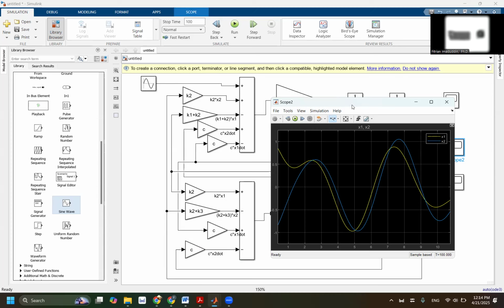But you understand that you still have all of this that's connected to this, connected to some other variable at the beginning. Minus C suspension x car dot, minus C suspension x wheel dot, minus K suspension x car, minus K suspension x wheel. This is the K suspension, x wheel, equal to what? Equal to F.